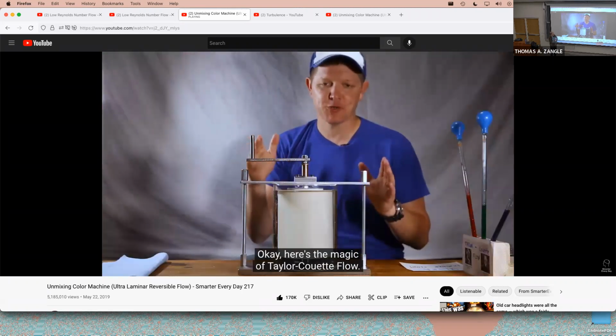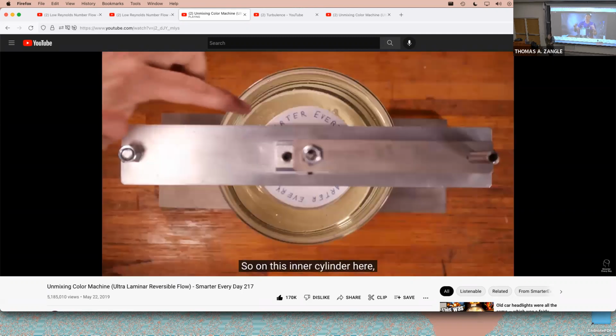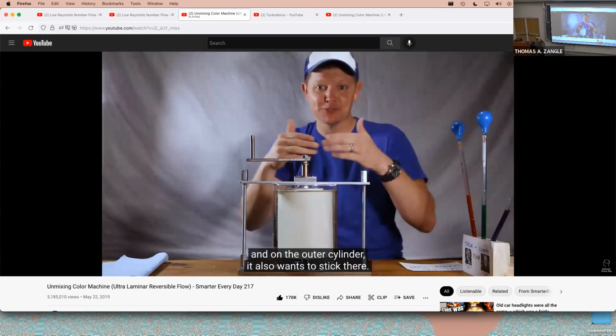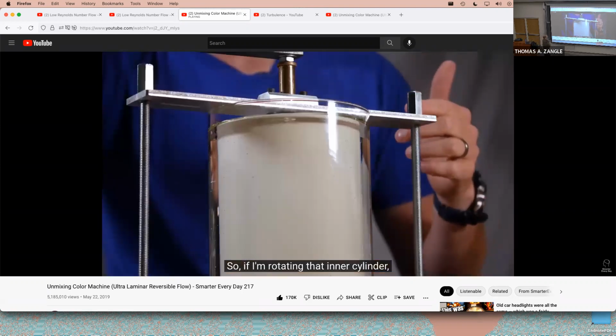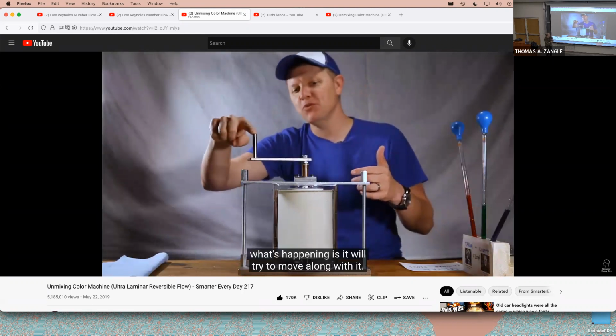Okay, here's the magic of Taylor Couette flow. We have something called a no-slip boundary condition. So on this inner cylinder here, the corn syrup wants to stick to it. And on the outer cylinder, it also wants to stick there. So if I'm rotating that inner cylinder, what's happening is it will try to move along with it.